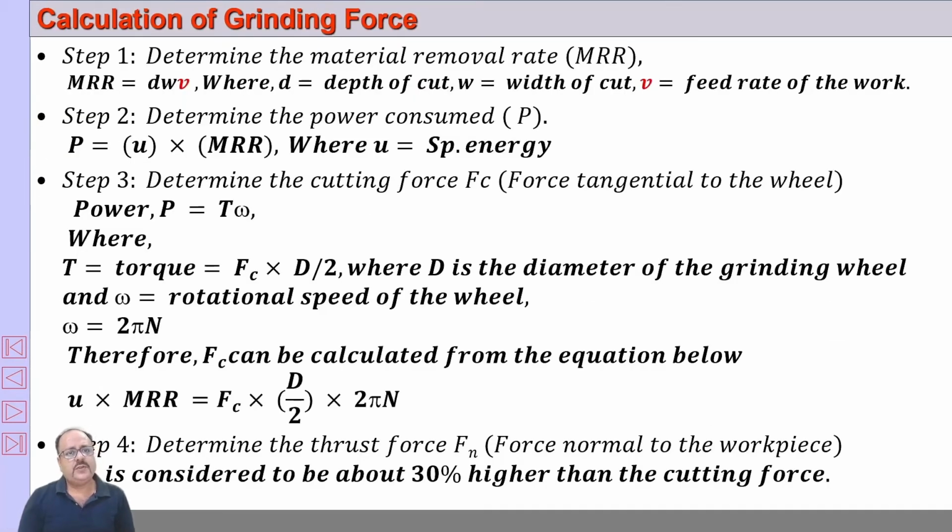So, calculation of the grinding force. How to calculate the grinding force? To calculate the grinding force, you need to determine the material removal rate. You know the depth of cut, you know the width of cut, and you know the feed rate with which you are machining. So if you multiply these three terms, you will get the material removal rate.